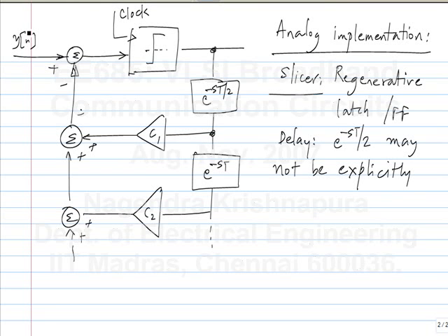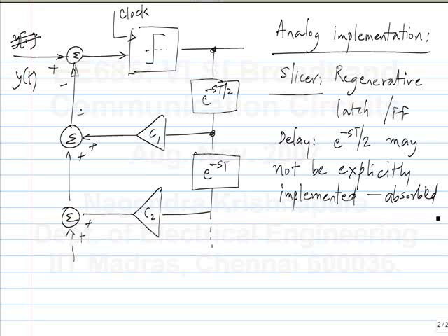So in this case, we are looking at, I say y of n, it's really y of t. You have to make sure that the cursor is normalized to 1. Okay. No, see, you are varying the taps, right? No, that's what, like, the value of C1 and C2 will be scaled by the cursor value also.